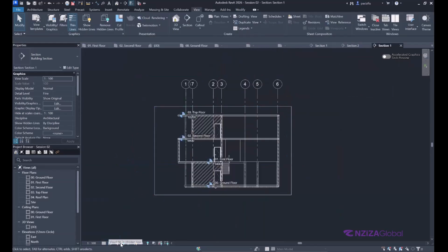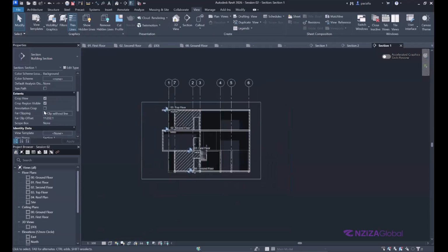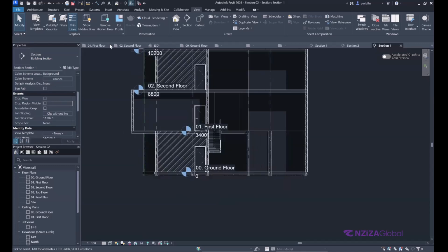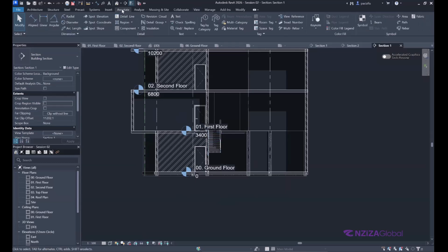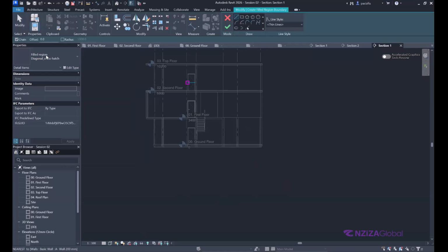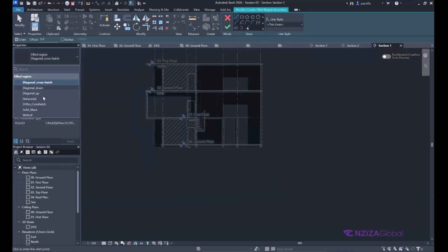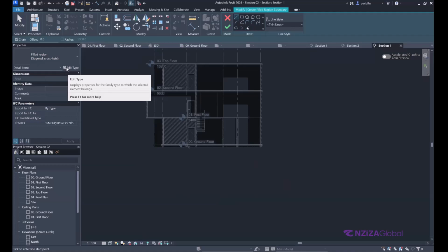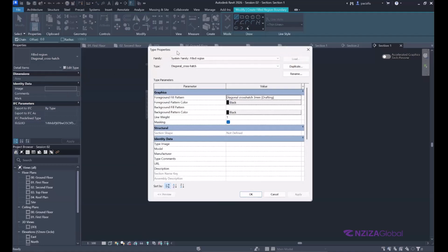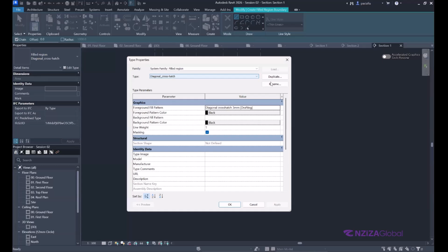File. So to have those kinds of fields, we just go to annotate region. Now we have different regions, different types of fields. We can take one and just edit it. If we go in edit type, we will have this, then duplicate this and rename it half field.